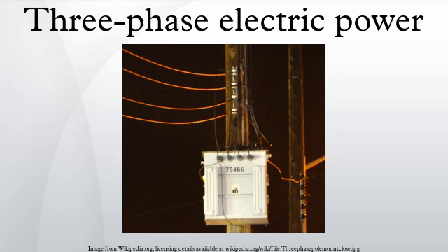and transformers. In a symmetrical three-phase four-wire, Y system, the three-phase conductors have the same voltage to the system neutral. The voltage between line conductors is √3 times the phase conductor to neutral voltage. VLL equals √3 VLN. The currents returning from the customer's premises to the supply transformer all share the neutral wire. If the loads are evenly distributed on all three phases, the sum of the returning currents in the neutral wire is approximately zero. Any unbalanced phase loading on the secondary side of the transformer will use the transformer capacity inefficiently.